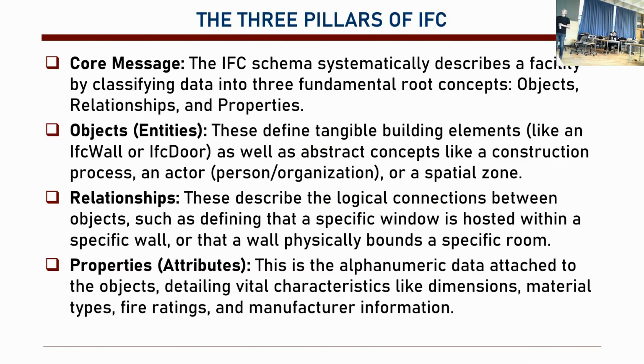And of course, we have objects, entities, like IFC wall, IFC door. We have relationships, like hosting something. A window is hosted in the wall, okay? Or a wall bounds a room. We can put many walls and say that these walls bound this room, okay?